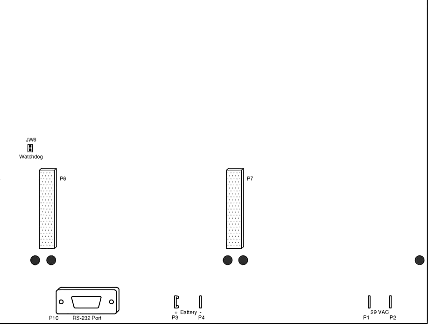Making our way to the bottom right of the QX Mini main PCB board, you'll see the connectors for the transformer, which are rated for 29 volts AC. On the board, they will be labeled P1 and P2. This connection is not polarity sensitive as the voltage is alternating current and is converted into DC or direct current internal to the main PCB board.